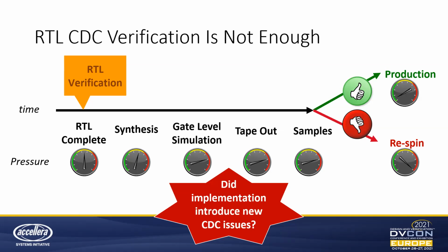Clock domain crossing (CDC) verification is a critical step in the design verification of a chip. CDC verification ensures that signals pass asynchronous clock domains without being missed or causing metastability. Traditionally, CDC verification is done on the register transfer level (RTL) representation of the logic of the design. However, during the synthesis stage, when the design is transformed from RTL to gate level, some issues like glitches can be introduced that may eventually lead to chip failures.